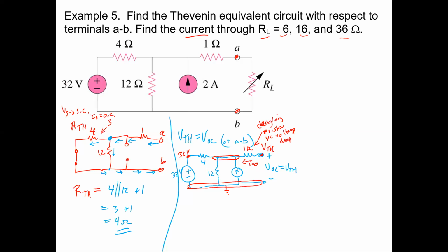Somebody remind me tomorrow to have you measure a dangling resistor voltage. You can just hook up a 12-volt source, put a resistor across it, and then your voltmeter, and measure that thing, and it's going to be the same as the voltage source, because you're not having any appreciable voltage drop when you have no current going through a resistor.